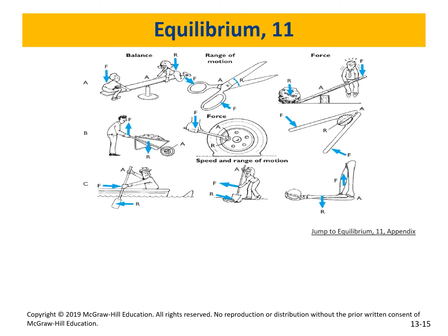So here, the first row, the top, these are class 1 levers, right? Why? If you have the center of rotation in the middle between the force and the resistance, that's class 1. So that's the center of rotation, force, and the resistance. So yeah, the boy is trying to pull the girl up into the air. Now here, in the scissors, you have two forces. This is your center of rotation, and you usually try to move these two sides of the scissors. So those are the resistance. So the center of rotation is in the middle. Here, this is the rock, this is the center of rotation, and this is the force you're trying to move. So that's class 1. Do we agree?